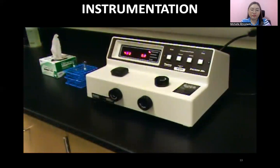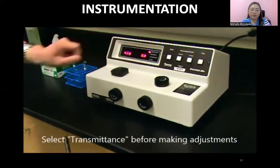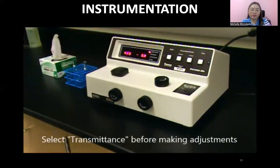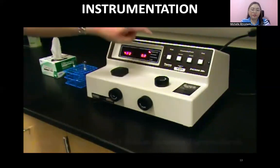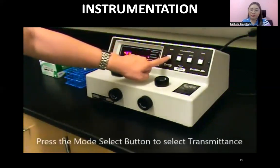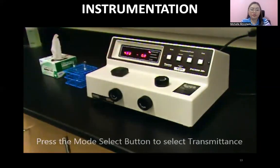When taking readings, it's best to go ahead and use the transmittance as the way to set up the machine and also to take your readings. The transmittance scale is linear, so it's easy to set the 0 and the 100%. So when you're ready to calibrate the machine, be sure to push the mode button several times until you have the transmittance value highlighted before you begin.